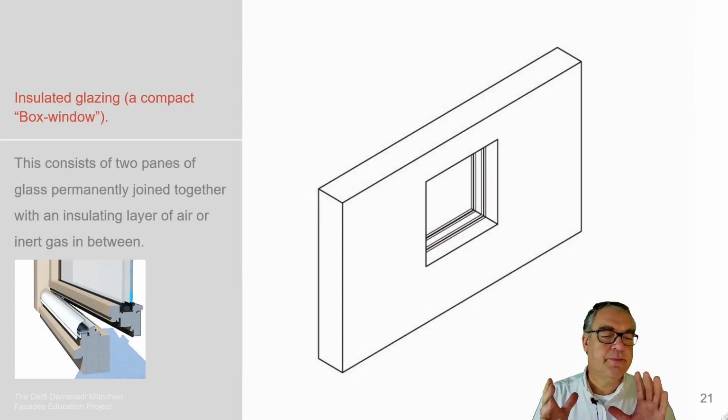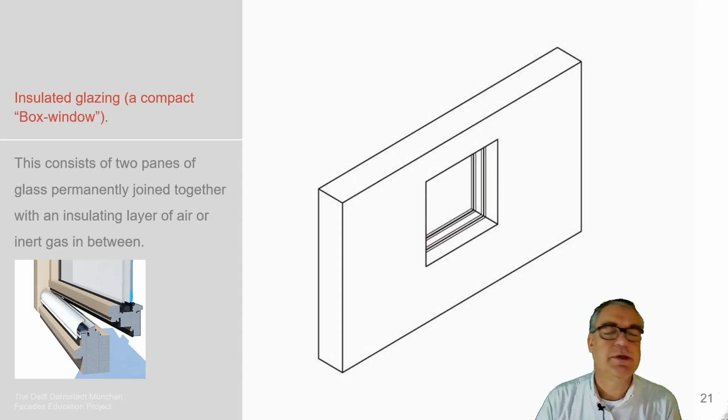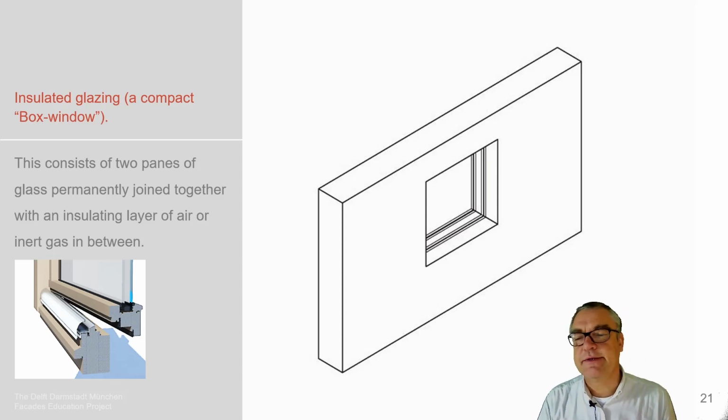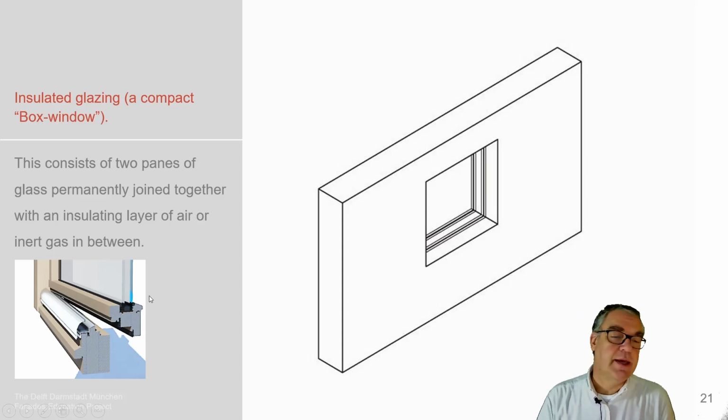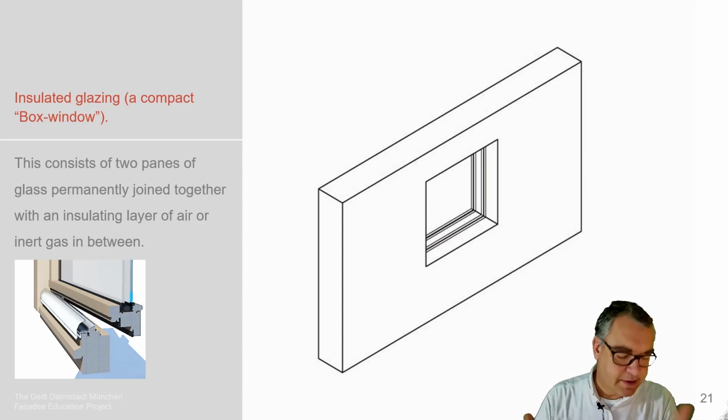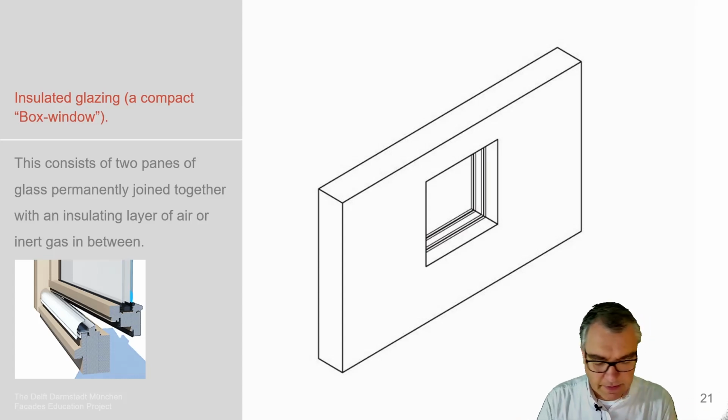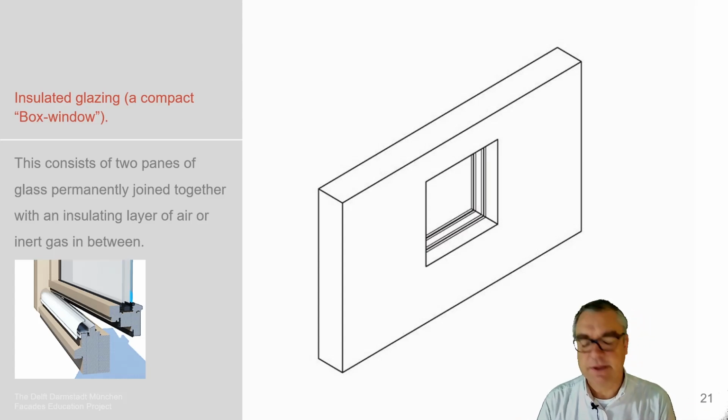And when the next level of window has to appear, the insulated glass units, IGUs, are investigated and developed. An IGU actually works with two layers of glass. We have an inner and outer layer. We have a spacer in here, and then this whole set is positioned in a frame system, to allow an openable opportunity for this system.